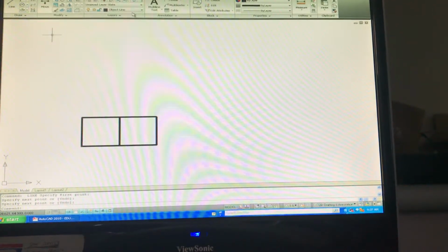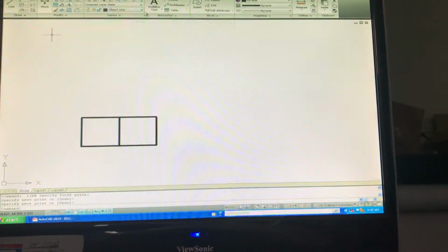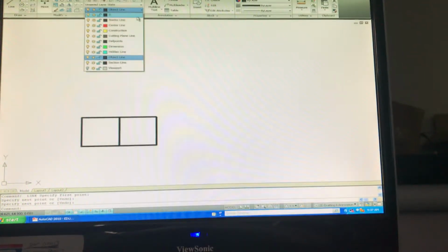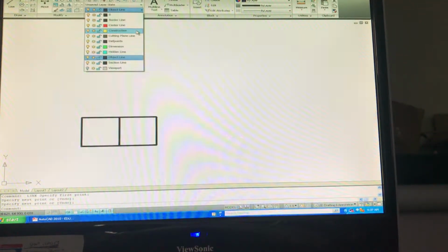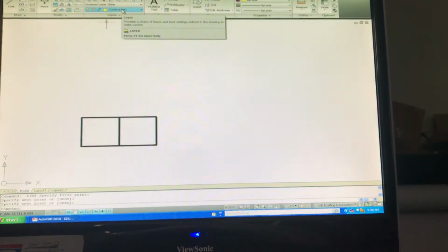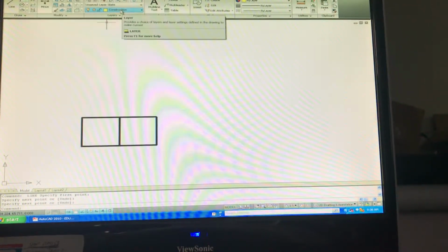At this point, what was our next step of our procedures in drawing a multi-view drawing? Draw the side view. We draw the next view by what? Drawing lines off the left, using construction lines and projecting them both horizontally and vertically. Right? So I get my construction line layer. Now this is something new, so pay attention.